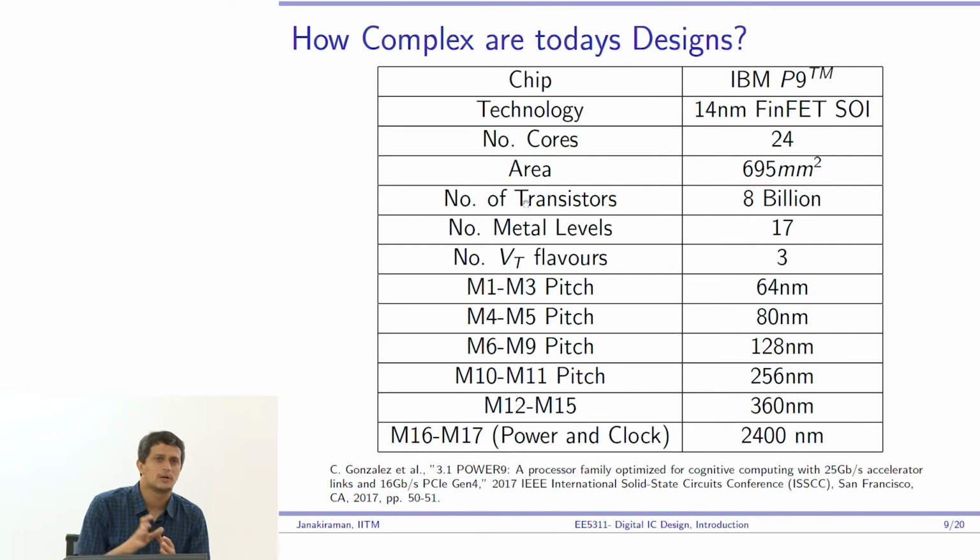So just an order of magnitude question, if the on current is, let's say, 1 unit, what will be the off current like? Order of magnitude. It's about 1,000th of the power, 10 power minus 3. That's what a technology can guarantee. Beyond that, it's very difficult, right? So they found it very difficult to achieve this beyond 22 nanometer with the old transistor technology.